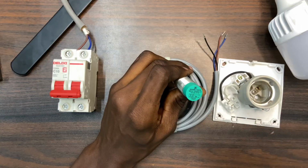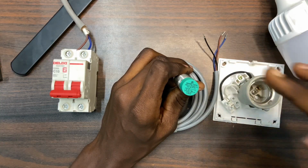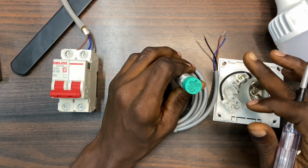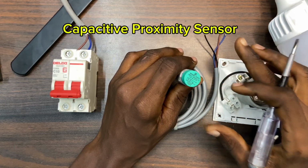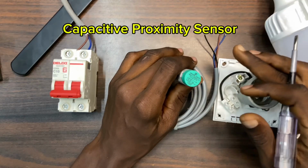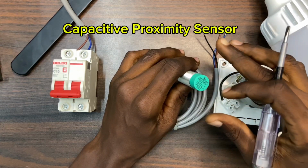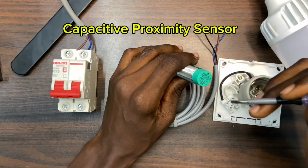Now, this inductive proximity sensor only detects metallic objects. It detects metallic objects using an electromagnetic field. Capacitive proximity sensor also detects changes in the capacitance caused by the presence of an object. It can be used to detect both metallic and non-metallic objects. That is the capacitive proximity sensor.